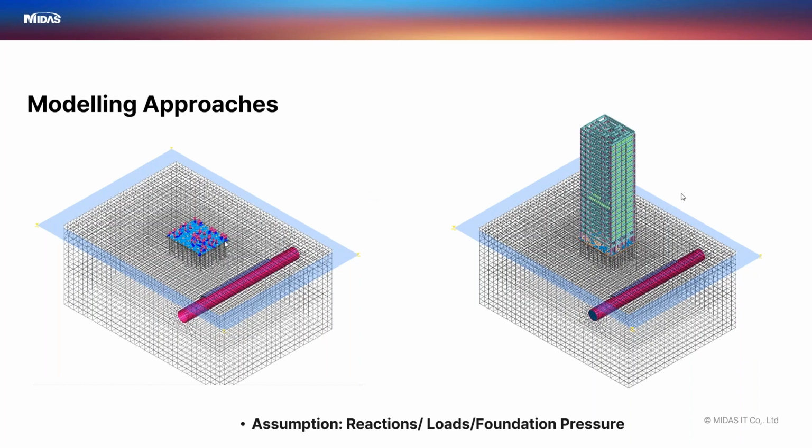Okay, so the difference is that in the absence of the building, which acts as a long slender beam, without that you will not see the angular displacement. Whatever you will see will be a UDL, because the entire load is applied on the raft. So it is sometimes better to check, if the tower is way too high, just to ensure that you get to check the angular displacement of the ground and also of the building, because it will not be the same in all directions. Okay.